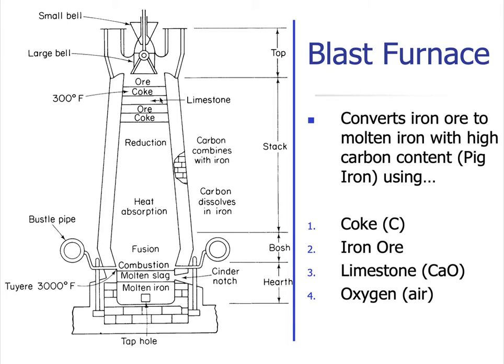Okay, so we have iron ore and then coke layers and then a little bit of limestone mixed in there, and we alternate those layers and they go all the way down to the bottom of this furnace. So this is probably 150, 200 feet tall here. The largest one that we've been to in Germany does 500 tons an hour, and the inside diameter is 55 feet. So these are huge furnaces. It's lined with a brick material that is magnesium oxide or something like that. It's an insulating material, okay? And it can deal with the heat and the slag.